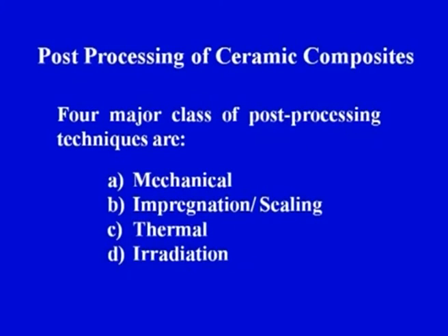Now coming on to the major topic for today's lecture, that is the post processing of ceramic composites. So 4 major classes of post processing techniques are there. Let me name all the 4. First one is mechanical, second one is impregnation or sealing, third one is thermal, fourth one is irradiation.